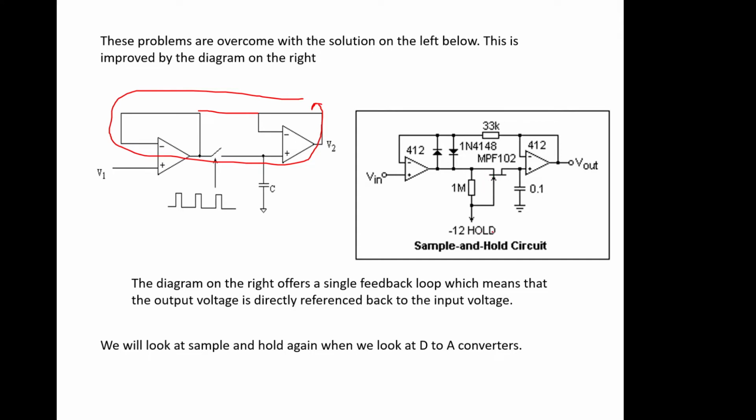So you can see that we're compromising this straight away in terms of its speed, but we've maintained a little bit of accuracy compared with this one. But these would work, and you can replace this switch with one of those switch capacitance ones, and it will work quite nicely with these two diodes in place here. So even the idea of a simple sample and hold suddenly becomes reasonably complicated, and this is a relatively simple one. There are lots of other ideas with multiple switches and things for charge balance and all kinds of stuff that you can make this really complicated if you want to.